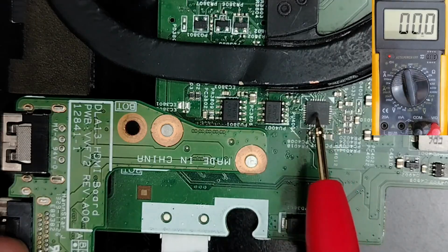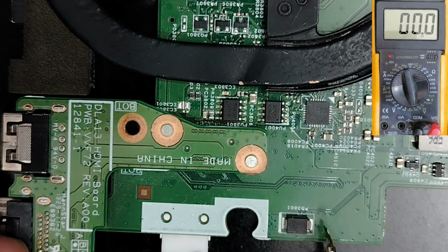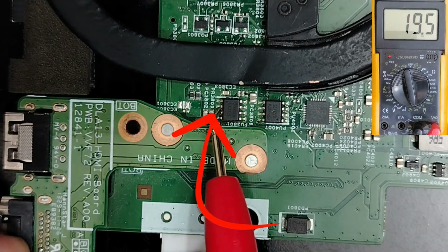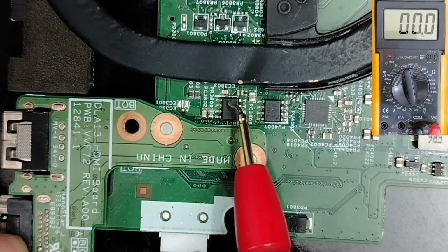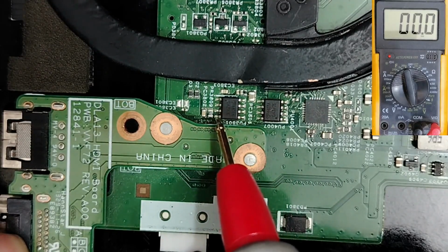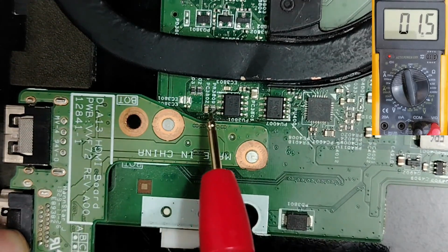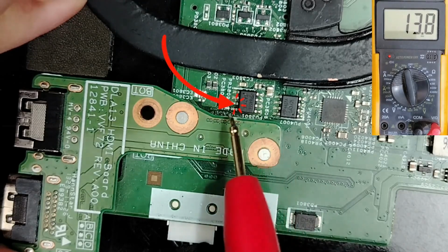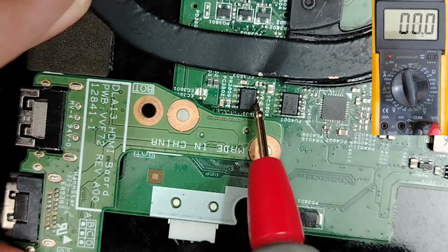Guys, you see here, this is the charge IC. Here we have the first switch, the second switch. The 19 volts will go to the first switch here. If we check here, we have 19 volts. As you can see, this dot or small hole means this is the source, and over here we have the gate. Let's check the gate. We have 3.6 volts on the gate. So the 19 volts will pass to this side. Why? Because the gate over here is activated, as you can see, 3.6. So here we have 19 volts.